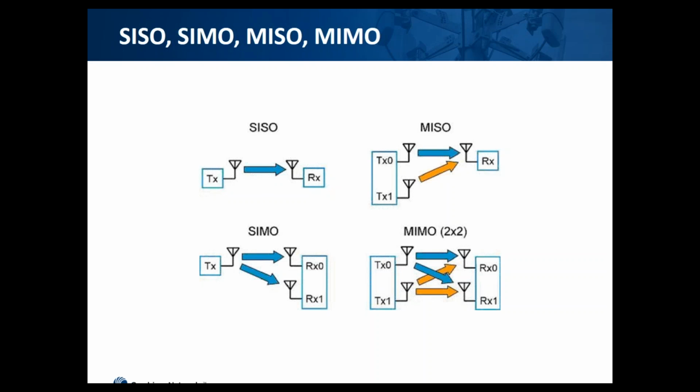The same is true for the multiple receivers. With two receivers, the received signal can improve significantly when the two signals are combined. But with 3, 4, 5 receivers, we start having diminishing returns, meaning that the signal might still improve, but not by much. As each additional receiver represents a cost, at one point it's not worth adding receivers if the signal is not significantly improving. This is why we don't see devices with 100 antennas. We can see 2, 4, or 8, but beyond that, you need to use different types of techniques to take advantage of the multiple antennas. Simply combining the signals doesn't give you any more improvement.